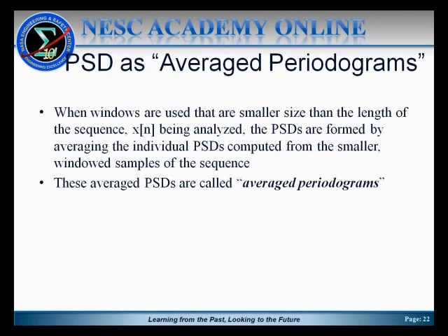When it's done in that form, they're called averaged periodograms. And that averaging helps, in addition to the windowing, smooth out some of the chatter that you get around the sequences, where spectral leakage combines real signal among adjacent sinusoids in the discrete Fourier transform. So that can be useful too. And again, this is provided primarily just so you know what an averaged periodogram really means.